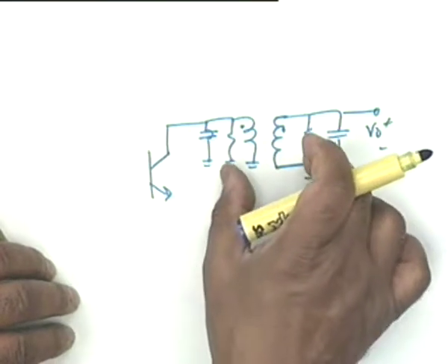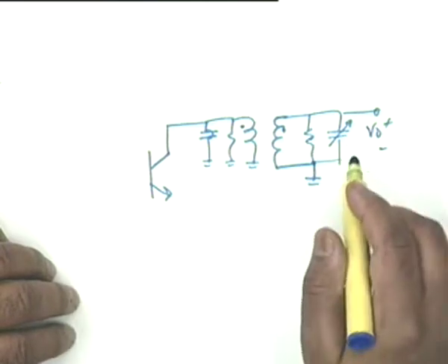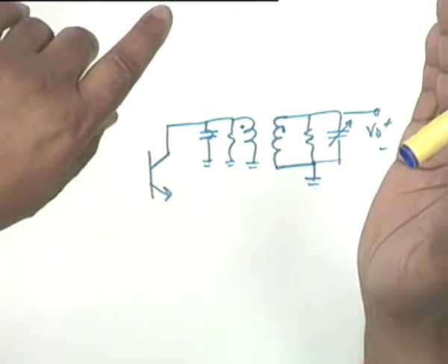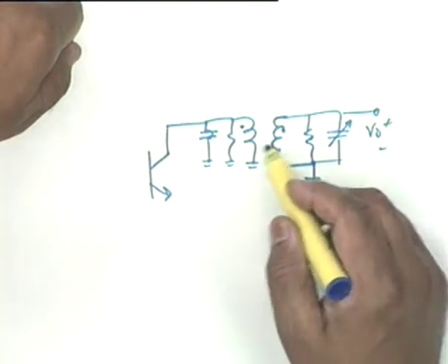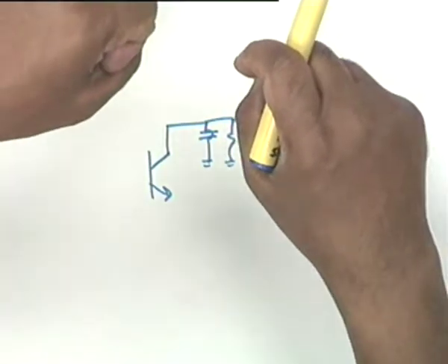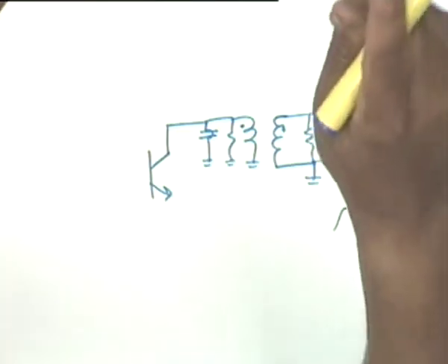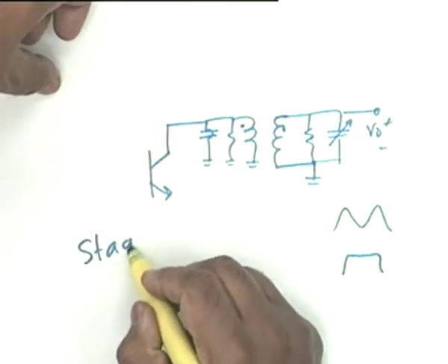All right. Since the two frequencies are not required to be identical, you can tune one of the capacitors so that the desired response is obtained, so that the tuning is staggered. That is, the resonance frequency of this circuit is not the same as that of this circuit, but their coupling is through magnetic coupling. As you bring the two tuned circuits closer together, as you tighten the coupling, double peaks appear. There is a critical value of coupling at which it would be maximally flat like this, and this is called stagger tuning.